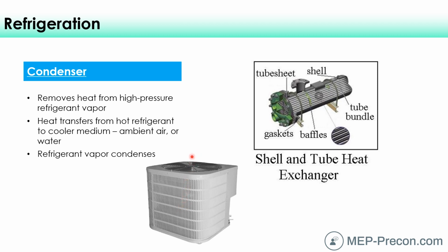So the BTUs that were generated or produced by the IT equipment inside the building, inside our IT closet, by all of those electrons flowing, the data and all those ones and zeros, that produces a lot of heat and BTUs. So we're going to pull those BTUs out, and we're going to reject it through the refrigeration cycle in a very efficient, concentrated way. So when you put your hand over that and feel that heat, that's not the heat being produced by here. It's just moving the heat from inside the building to outside the building. So that's how that condenser works within an air system.